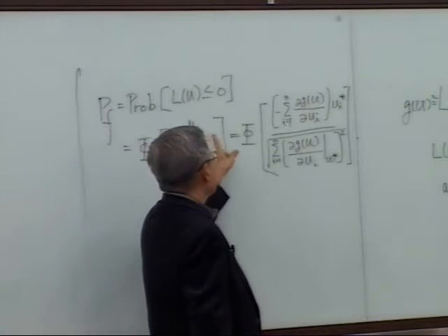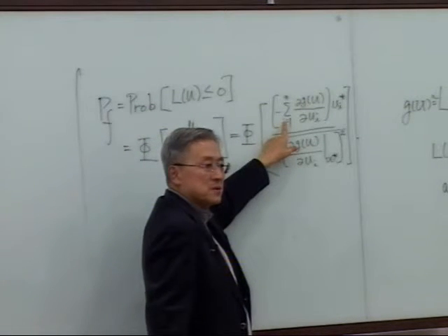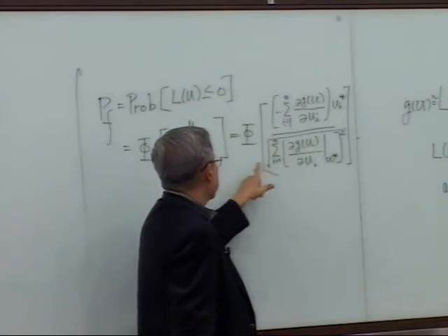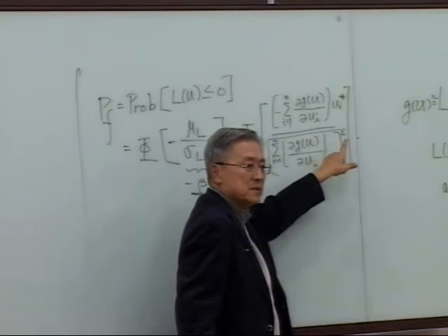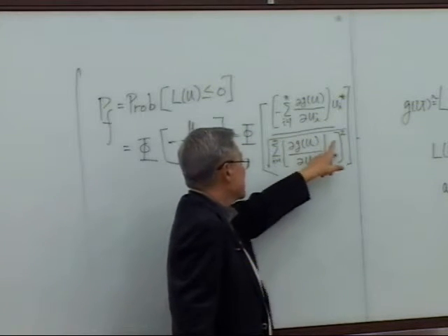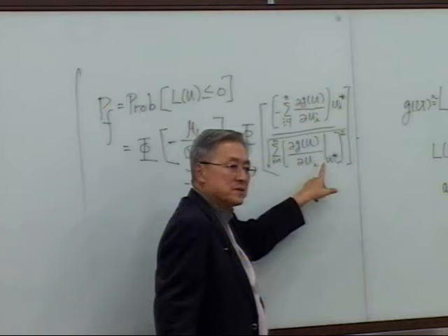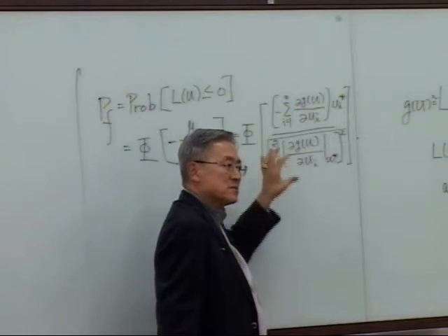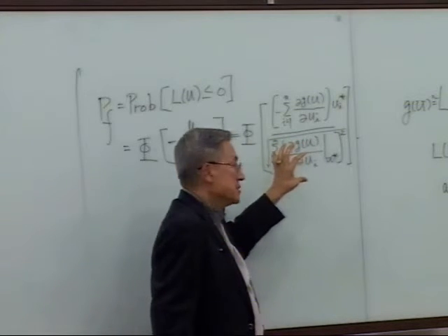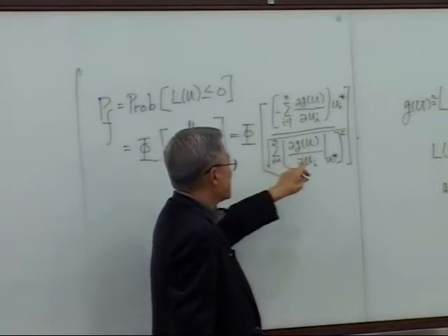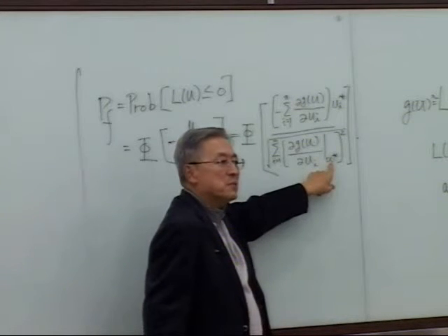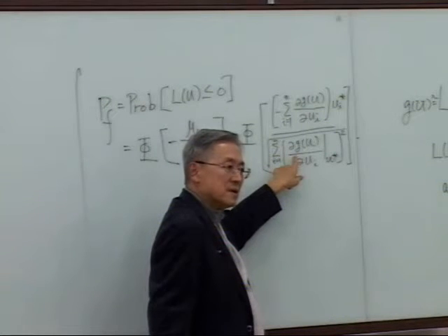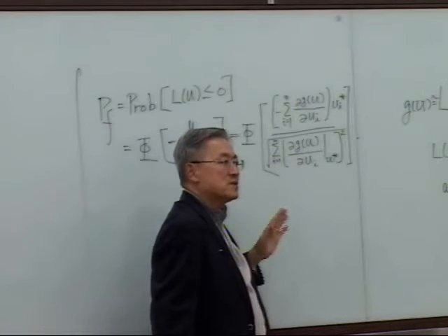Beta, and mu L happen to be this, which is A naught, and sigma L happens to be the square root, because it's standard deviation, squared, evaluated at the MPP point. So to solve this problem is again to find first the MPP point, then evaluate this at the MPP point, then it's done.